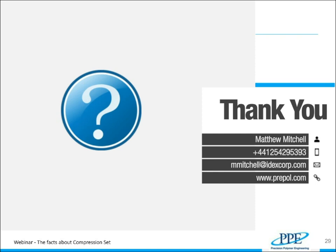Okay, so first question, Matt, is can I just squeeze the seal a bit more to compensate for compression set? I think we touched on this slightly in the slides, but in the short term, yes, people do this for short-term applications where they're worried about very short-term excursions to high temperatures, but the compression set will always be progressing over time. So eventually, this increased squeeze will be overcome by the compression set, and you will still potentially have a failure through that.